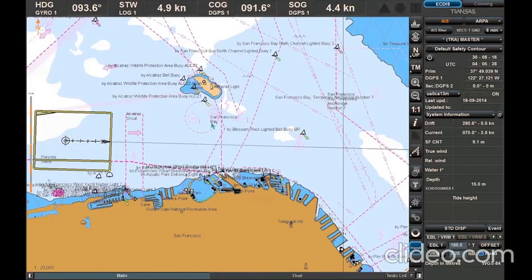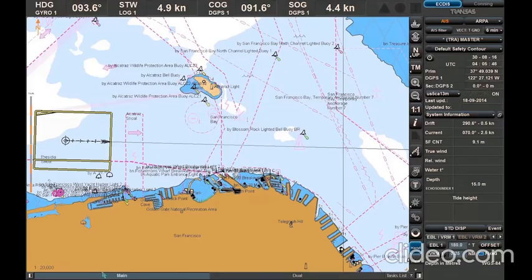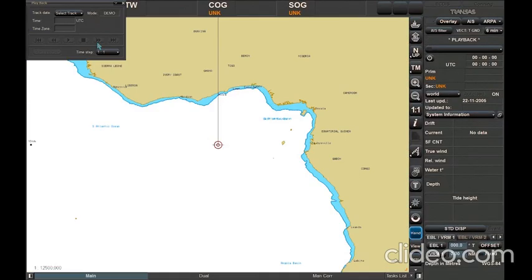Playback utility. Click the Transas integrator and select the Playback utility button. After the utility has run, the screen will display a control window. The playback window is intended for the selection of the date and time of the situation that should be played back, and for the control of playback.